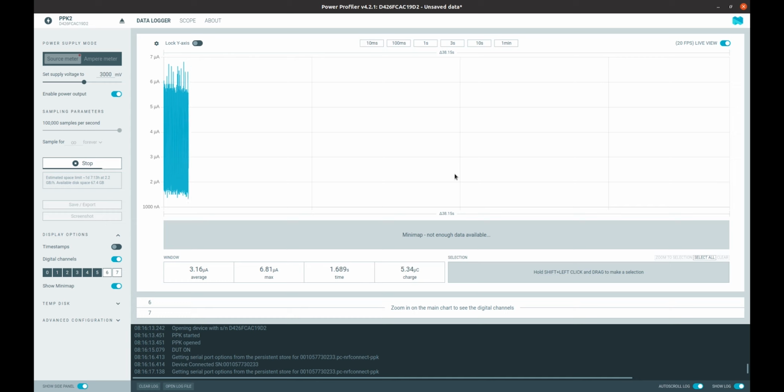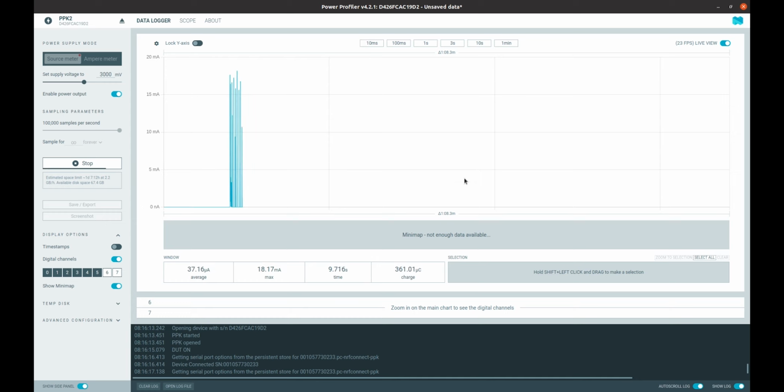Yeah. LIT also supports the active mode trigger feature. In this sample, it's triggered on the button press. So you can see the device is sleeping. I'm pressing button number 3, and it becomes immediately responsive because the interval was changed to fast polling. Now you can, for example, easily reconfigure it or commission it to the second fabric.